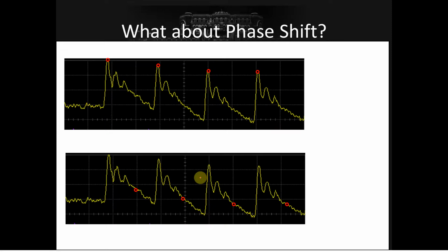What's that about? So what this is about is showing you, relative to that clock, we may want to sample right there, but that might not be good because we're right on the very brink of this point. And it may be that where we care about is somewhere further down the waveform. We may want to sample right here. So we add this delay between whenever the actual clock edge was, somewhere back here, to where we sample.